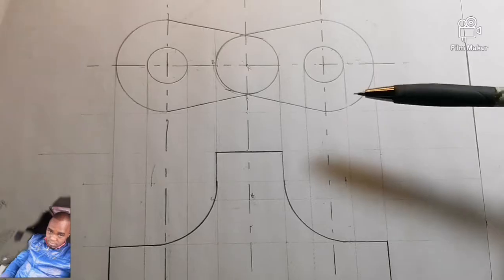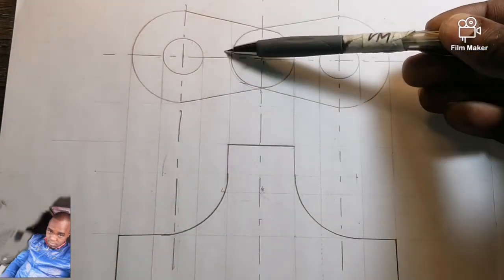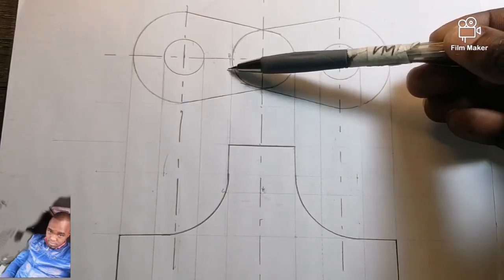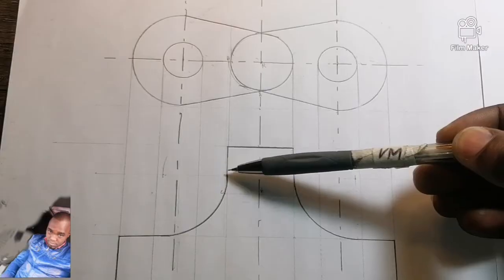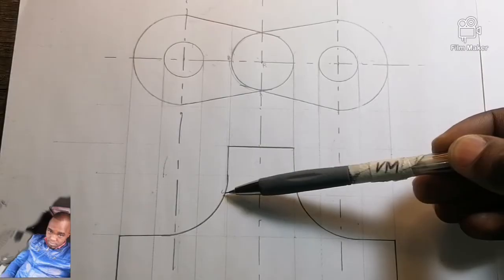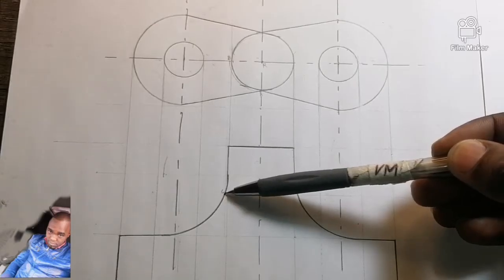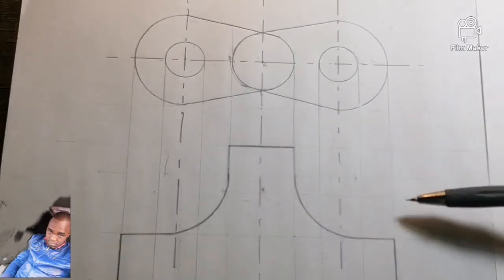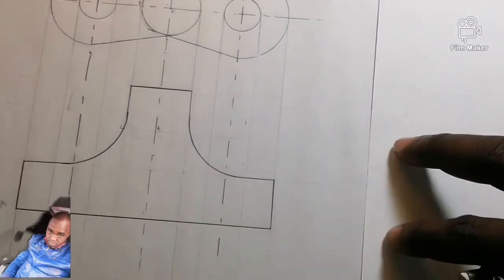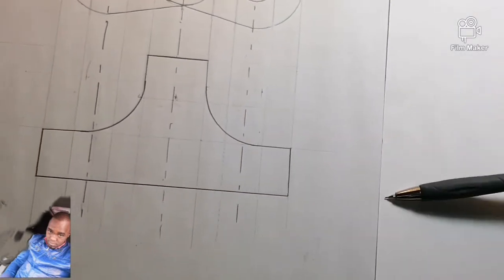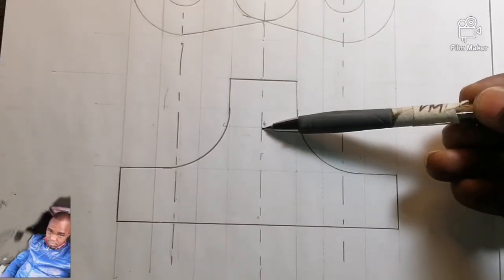So same applies to this one. We've got R there, A, B, to your center. Once it touches your center, it goes down to your front view. Once it touches your arc, it's point C, isn't it? Then it goes horizontally, and it will also give you your left view, regardless of whether the question asks you to provide the left view. You understand? So that point is your highest point.